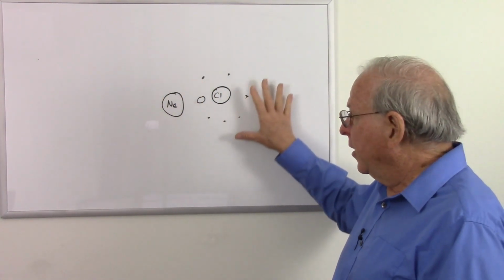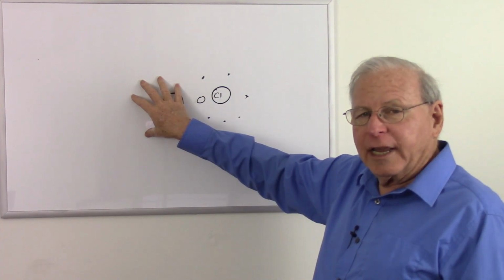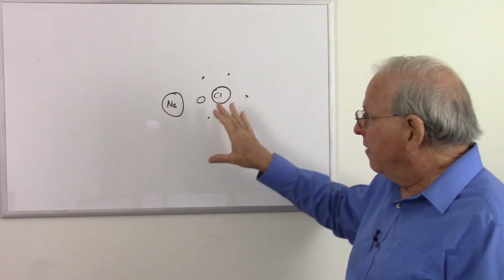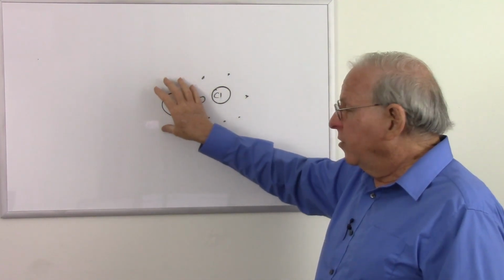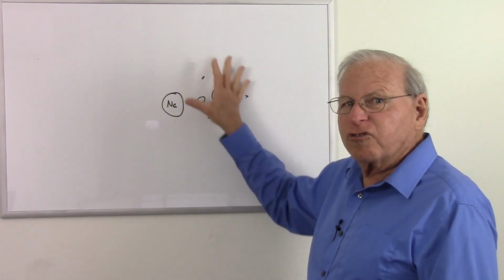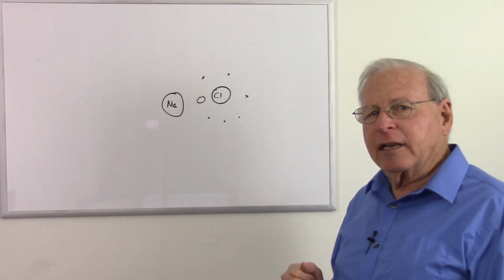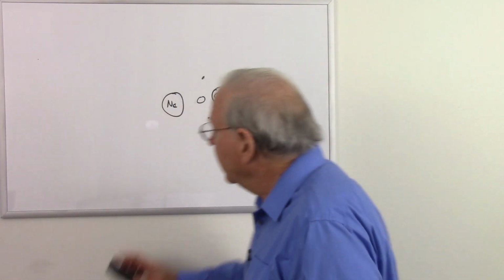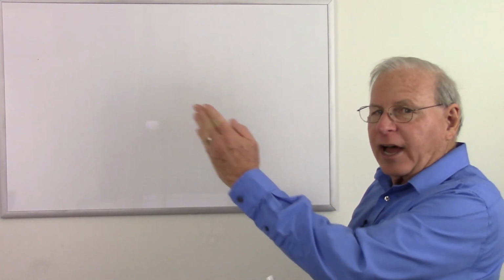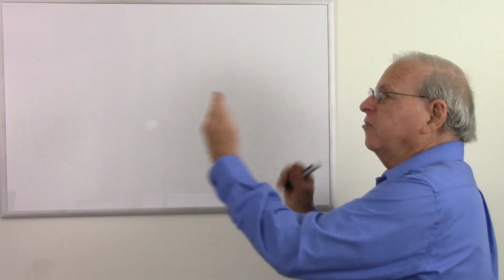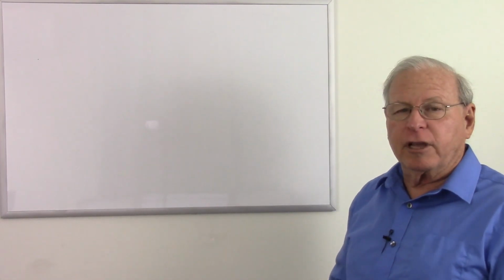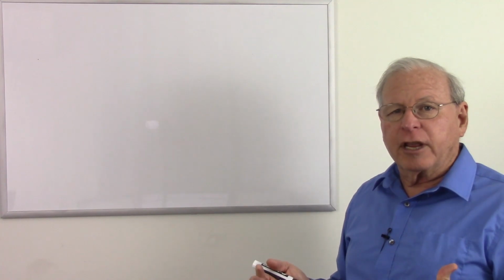That's what's called an ionic bond, where an element with 1 electron basically gives up that electron to another element that has 7 electrons that wants to have 8. They stay bonded together because this sodium atom is bound to this electron, and so we form this structure we call sodium chloride. The next kind of chemical bond I want to talk about is a metallic bond, and this is formed by materials that tend to be to the left side of the periodic table, about 2/3 or 3/4 of the periodic table is going to be your metals, which of course sodium is one. If you put a bunch of sodium atoms together, you get a metallic bond.